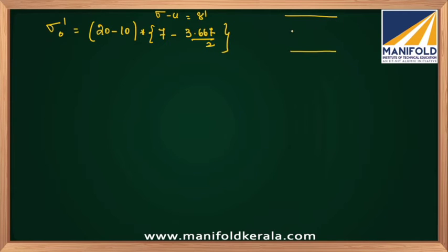The load distribution starts from L by 3 from the base of the pile. In that case, the bottom 3.667 meter of the clay is going to attain consolidation.